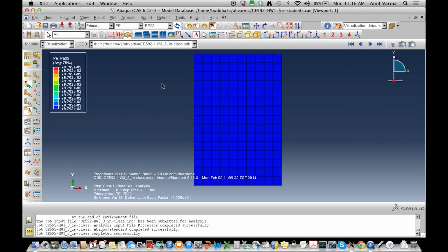Does that make sense? Well, if I remember this right, the normal to the surface will be along that 45-degree line, which means that the projections of the two plastic strains will be the same. But this problem is too easy. This gave me things that are not really teaching me anything. What I really want to see is I want to apply a loading condition that will reveal to me that it is following the stress states move on the ellipse. That's really what I want to see. And I want to see how those plastic strain increments are following the Prandtl-Reuss relations, which have disappeared.